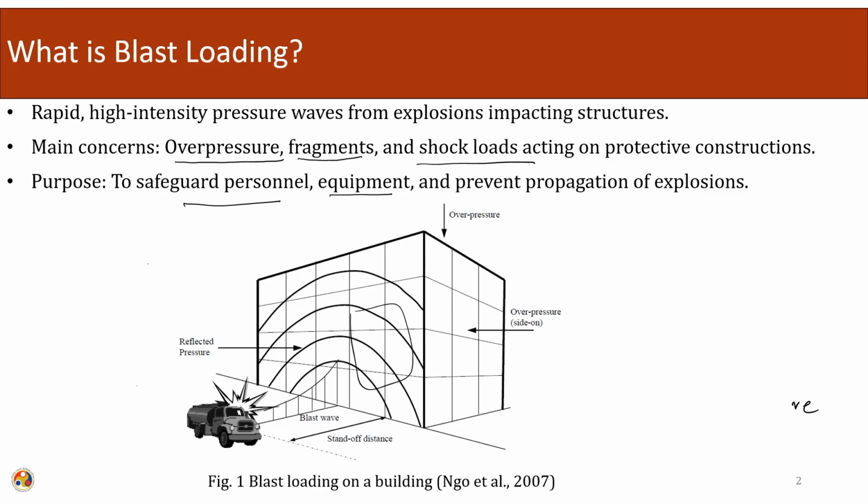Let us say the building is serving as a data center or it is storing high ammunitions, so we have to protect the equipment associated with it, and also we need to prevent the propagation of the explosions. Once the blast pressure hits a structure, there will be reflections, and due to the reflections the intensity of the pressure will increase.